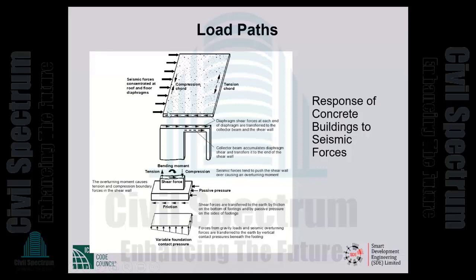The edges parallel to the earthquake, or the inertia forces, develop shear. Those shear forces are transferred to the supporting shear walls or frames. And those shear walls or frames, the so-called vertical elements of the seismic force resisting system, bring the forces down to the foundation, which takes them down to the ground, where all loads ultimately belong.